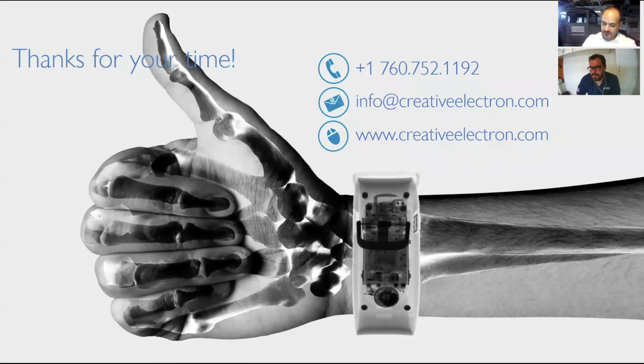We have another question. Are there any issues with the location of passive components? I think this question refers to one of the slides where you showed a QFN, and the board was pretty much empty, and there was one passive component right on top of the pins, basically blocking any chances of finding a short circuit between those two pins. Were there any issues moving those?